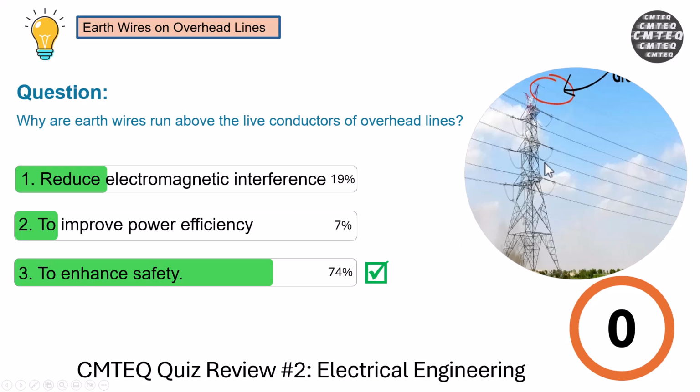fault. So, when the lightning strike is going to come from above, before it gets to the three-phase lines here, it's going to first get that earth. And the lightning's intention is not to get to those wires, the lightning wants to get to the ground. So by placing that earth wire above, you're providing the lightning with the shortest path to ground, so it doesn't have to find the ground here. You can just get it there and straight to the ground.